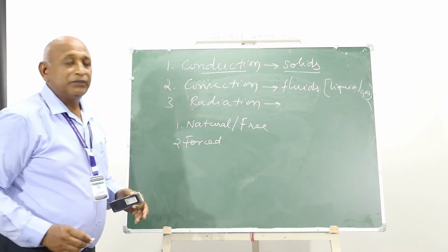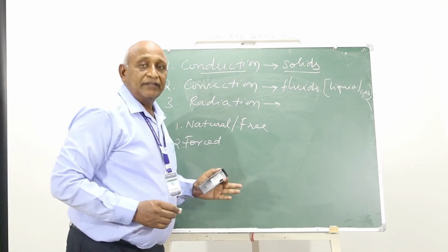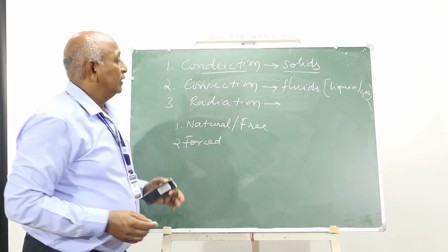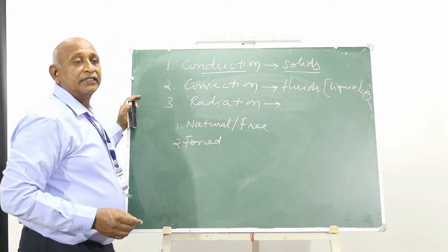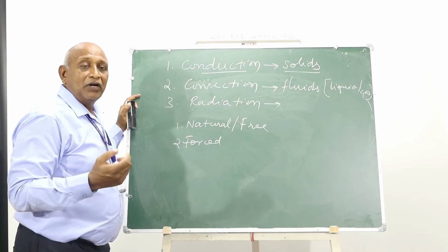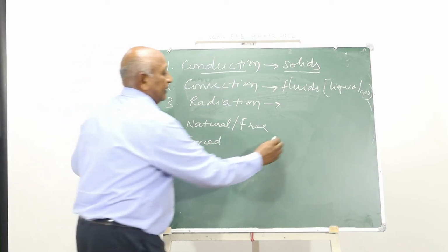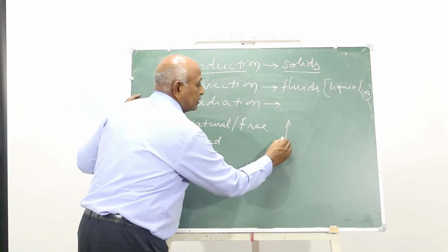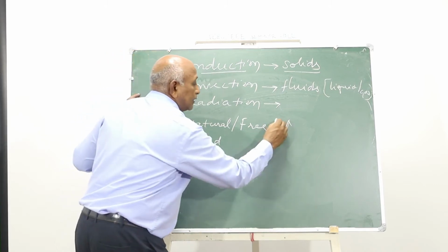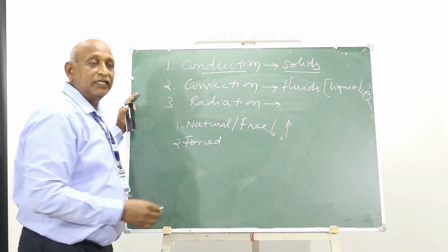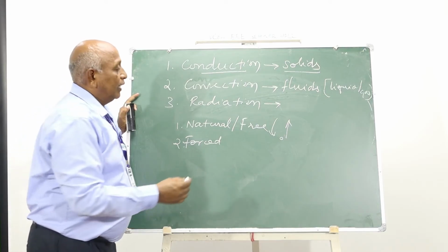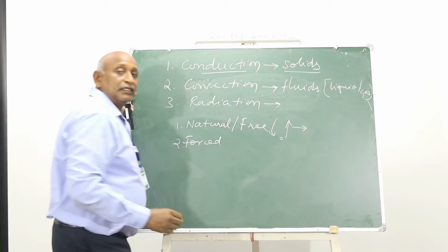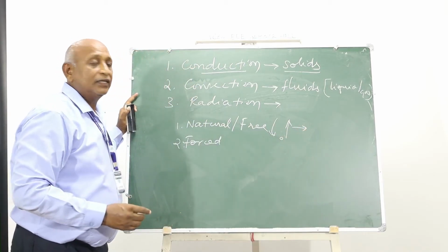In natural free convection, the heat transfer is due to the difference in buoyancy, where the fluid molecules get heated, the heated molecules' density decreases and they move upward, whereas the higher density particles will occupy the space. Likewise, a circulation current is created naturally due to buoyancy and the heat transfer takes place. A good example for this is heating of water in a vessel.